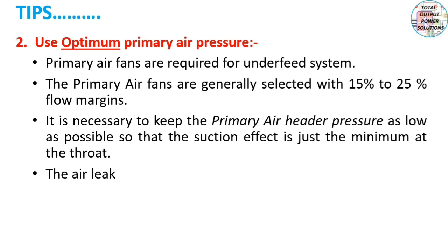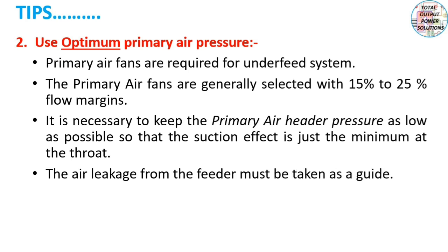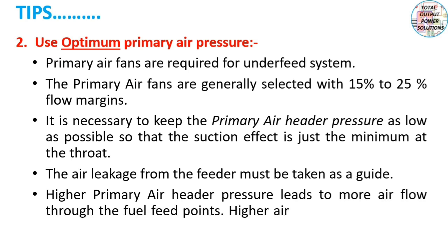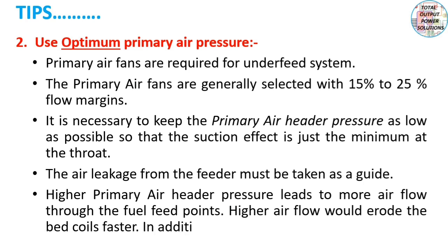The air leakage from the feeder must be taken as a guide. Higher primary air header pressure leads to more airflow through the fuel feed points. Higher airflow would erode the bed coils faster. In addition, venturi erosion would also be faster.